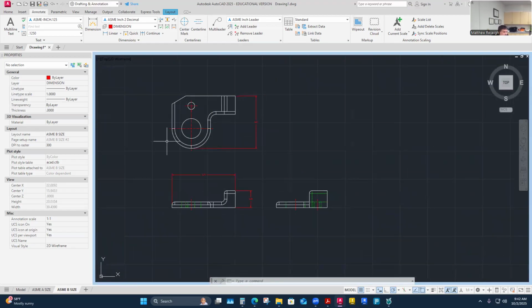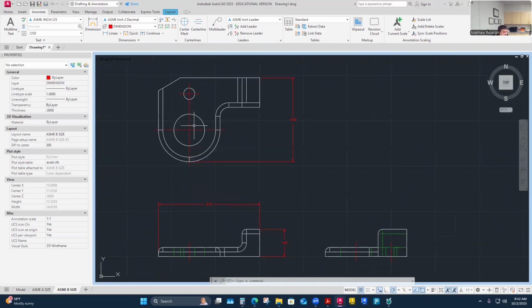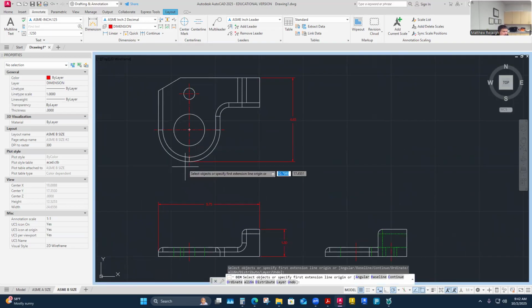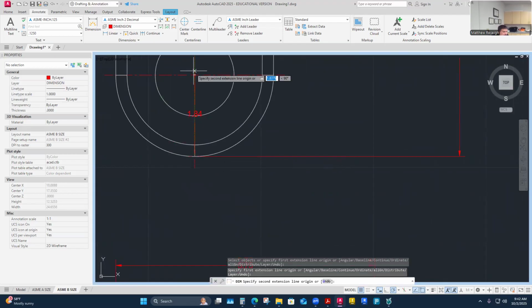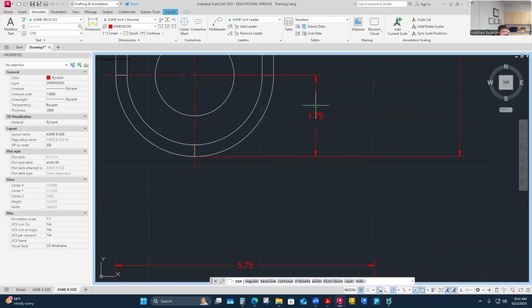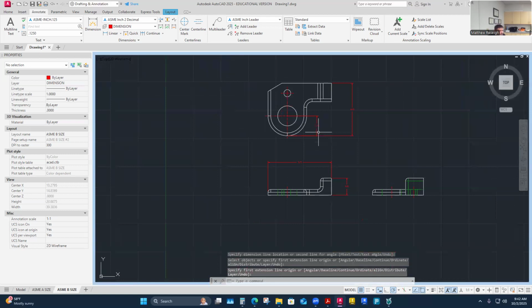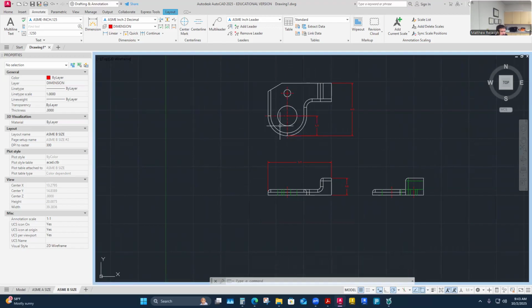I always think to myself with simple parts, I'm overcomplicating it if I'm establishing new ones. And what I mean by that is maybe I would come over here and I would go like this, and this would be the dimension that I think I should put in. Well, to me, you've just established a new datum. You're pulling that information from, I liked this surface better, and then you pulled here. I'm like, well, now you've just kind of established a fourth datum in a way.